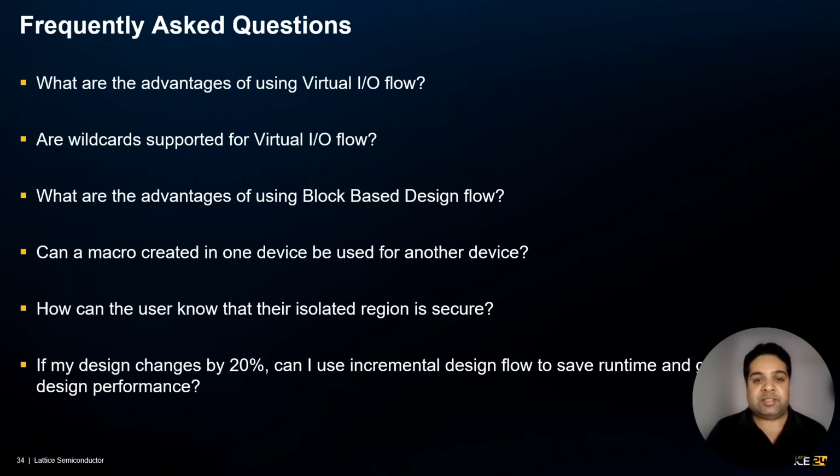If my design changes by 20%, can I use incremental design flow to save runtime and guarantee design performance? No. Incremental design flow is more effective for smaller changes, approximately 5% of the overall design. If users change more than 5%, then it's going to be really hard for the tool to maintain and guarantee the design performance and also save the runtime.